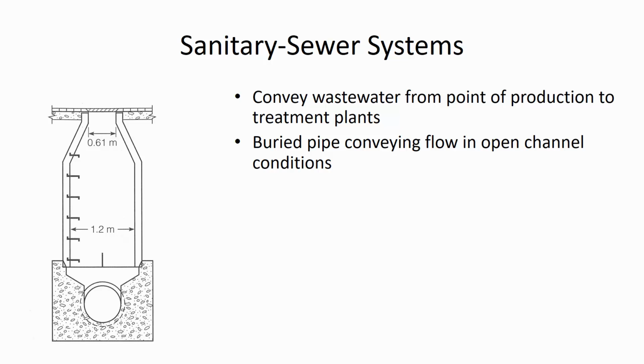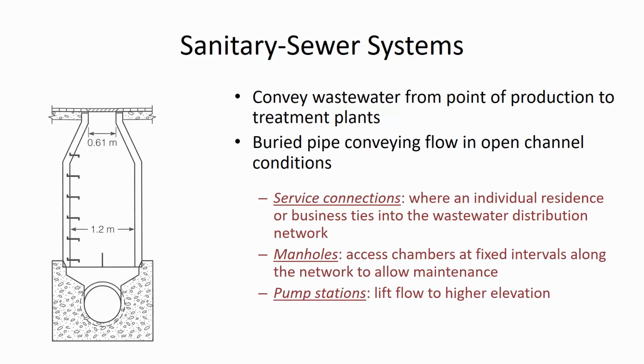And you'll remember way back we did a comparison of the Darcy-Weisbach equation and the Hazen-Williams, and Manning didn't do so great in that head-to-head comparison because that was pressurized flow. But in this case, it's not pressurized flow. It's flow that's flowing partly full.